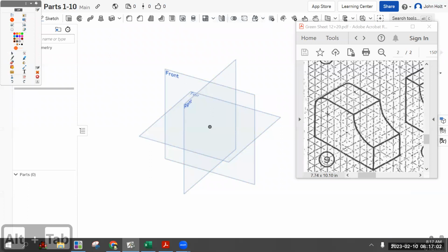Again, clearly, well, I wouldn't say clearly. You could do this in a single complicated sketch, mostly rectangle with some other stuff, and then do a single extrusion. We're going to do it in 3 separate steps. We're going to make a basic rectangle. That's the total height, total width, and extrude it the total depth. Then we're going to cut away this curve by making a circle and cutting extrude it. And then we're going to fillet it off.